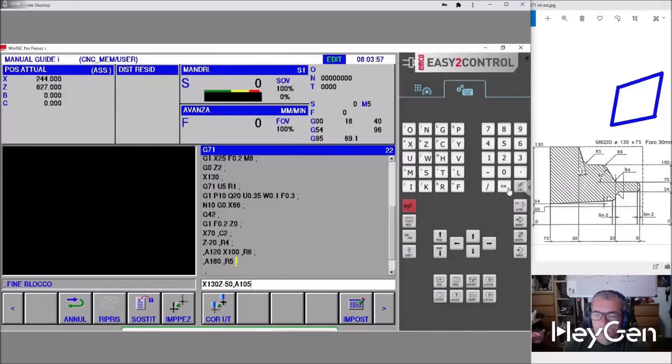N20 is my Q20. G40, EOB, insert. G0, X300, Z300. To avoid an alarm, we add an M30. Let's do our first simulation and see if we have any small errors. That can happen. Simulate. Let's rotate the piece according to our viewpoint, so ISO, X and Z in this direction. Let's restart the program and give it the start for the movement.